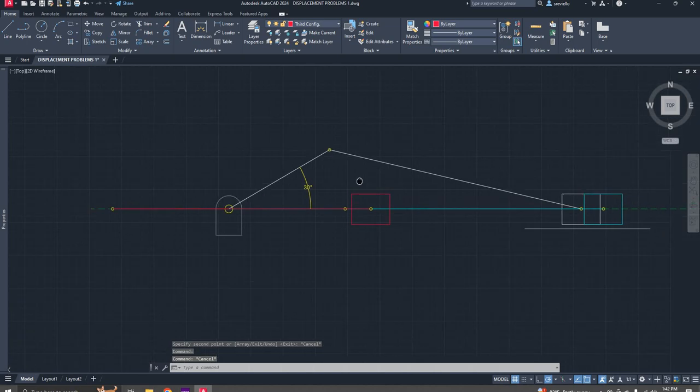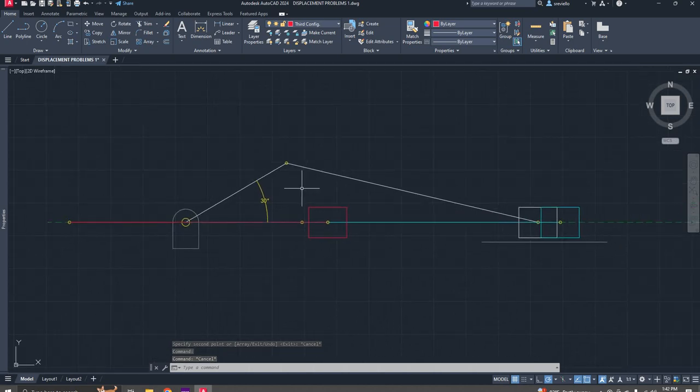So we take a look at what we just did. We see that as this crank, as this driving link rotates around this point here, the rotating link and the connecting link will be collinear here, and in that case our piston will be in its utmost extended position that way.